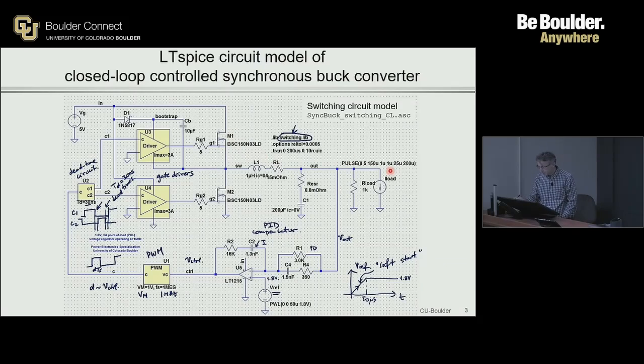That's again just a very, very quick summary of the circuit that is given in the homework assignment. Take it and do the assignment, but I would also encourage you to poke around a little bit and learn how various sub-circuit blocks here work. Look at the signals here, C1 and C2. Look at these gaps right here that we are forming. Look at the function of the pulse width modulator. Go inside the library and examine how these sub-circuits are actually implemented.